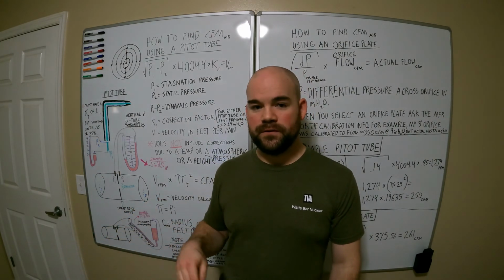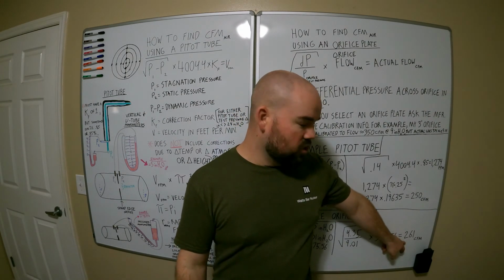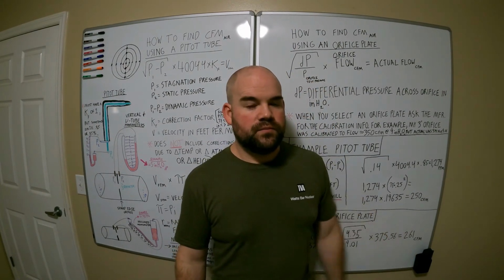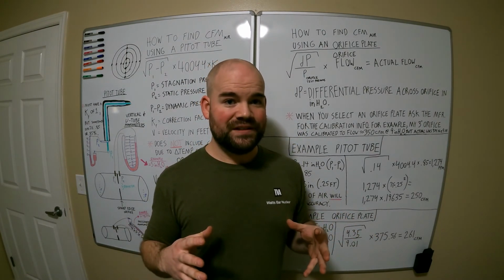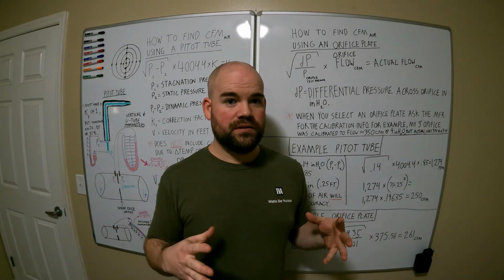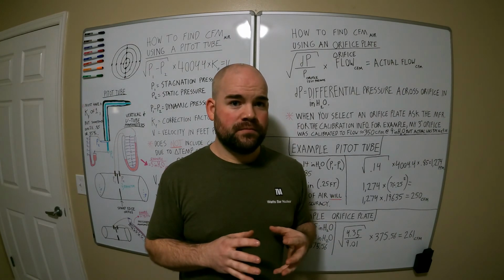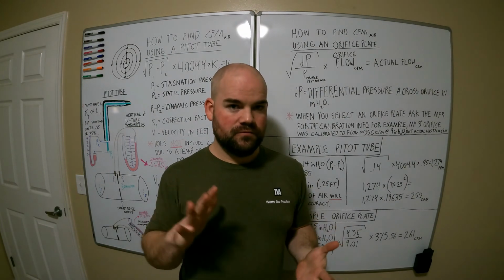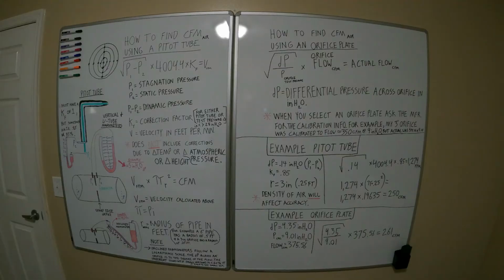Okay, the guy that built it to flow as much CFM as possible, average flow, and we're going to talk about that, your gross and net flow, we're going to talk about that too. That guy's going to win, because if you can flow 300 cubic feet per minute, and you just increased the amount of oxygen in that same 300, you're going to make a lot of power. If you're the guy that has 200 CFM of flow at peak lift, and you introduce additional oxygen by increasing atmospheric pressure and pushing those molecules closer together, you're not going to increase your power.